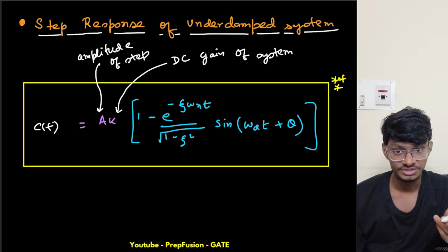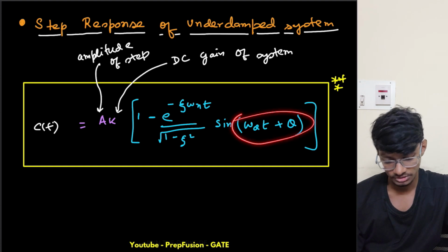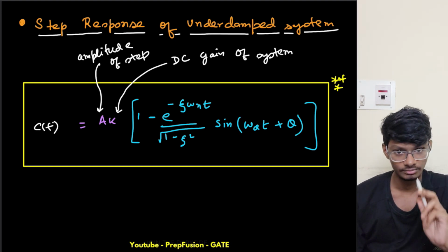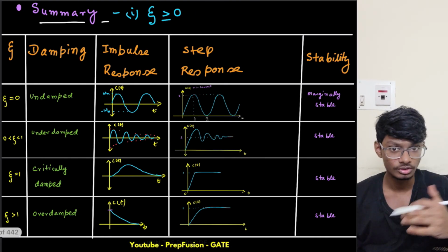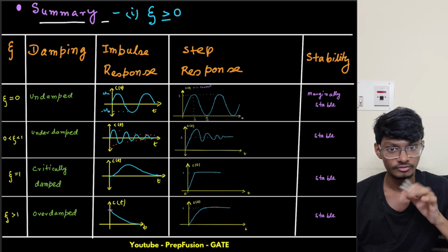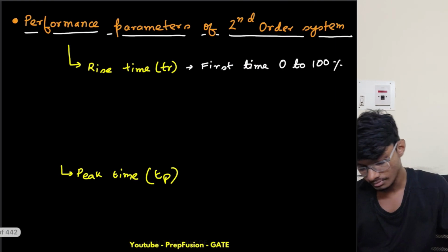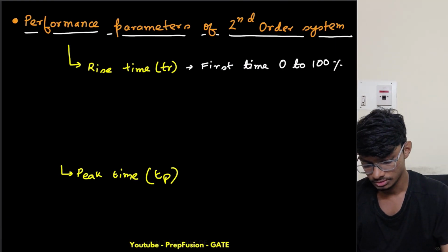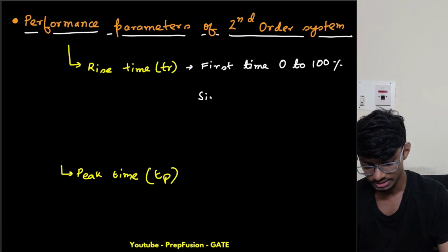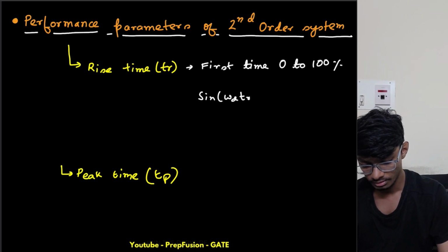Now the next option, what do I have? I have this one equal to pi, right? That's why that pi term came. So that's how you recall and remember the formulas. If you know the derivations, from there also you can understand how to remember the formulas. So basically I have to make this sine(omega d t_r plus theta) equal to 0.